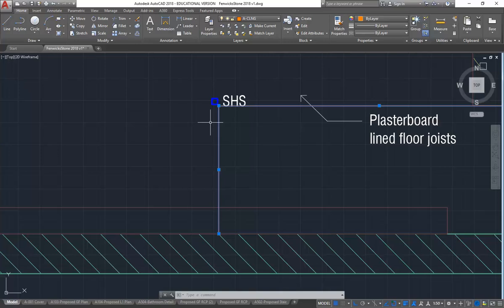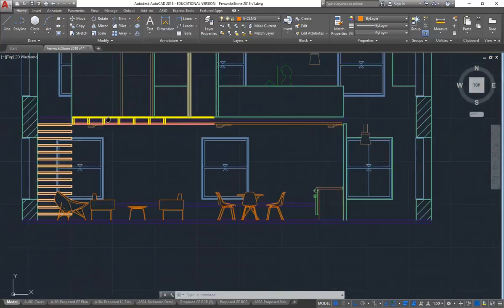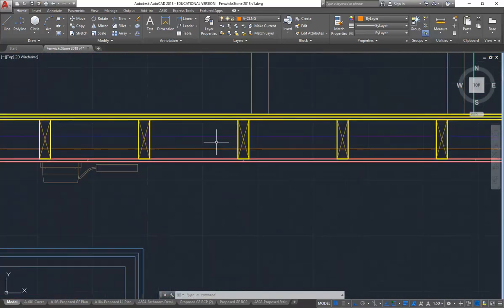Do you know what a fascia is? Yeah, pretty much, that's right. That's a good way of thinking of it. It's the cover, the edging. So here, the ceiling and the floor, if we go into that section I showed you earlier, that's the floor structure. Then we'd have the ceiling lining on the bottom, and the floor lining on top. And that would all need to be covered by a fascia piece. In other words, a trimmer, a piece of timber that covers from the top to the bottom all of that lining and the structure as well.